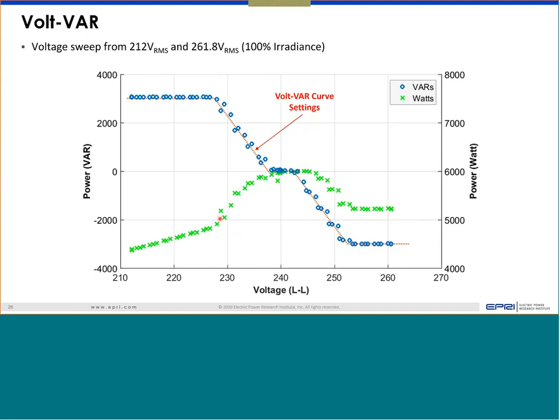And once it is current limit, it has no room to increase current any further. So after that, if we keep on reducing the voltage, power will keep on going down. Because voltage is low, current is fixed, power is going down. So that's exactly what is happening in the low voltage side. Thanks for the answer. So this type of behavior you'll also need to explain the inverter operation at different voltage range.